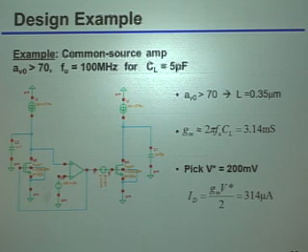And then I'm just going to take that and use it as a bias for the real amplifier that I'm going to measure. And then the only additional trick I played here was I added this little voltage source in. That's kind of like the small signal voltage source.